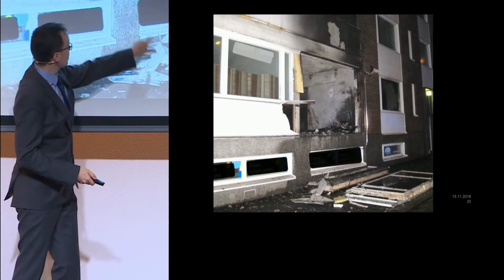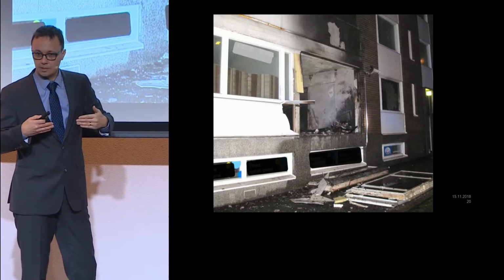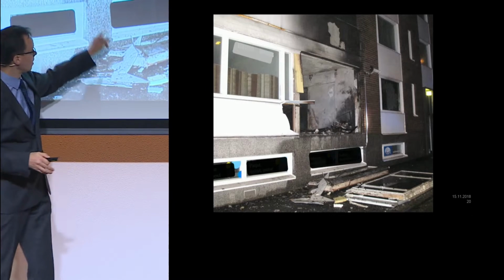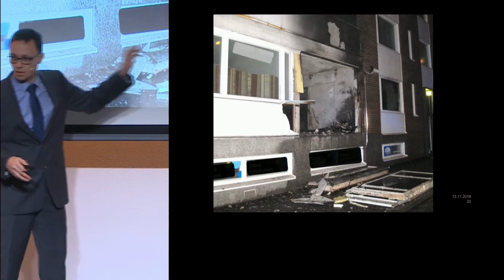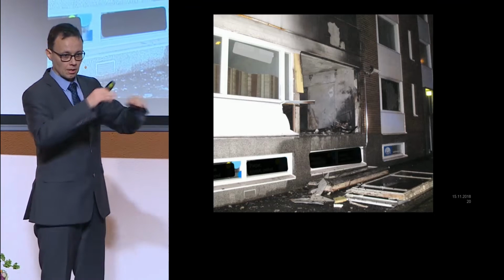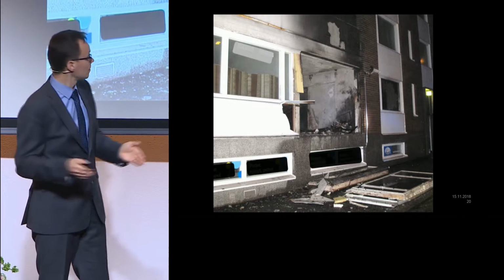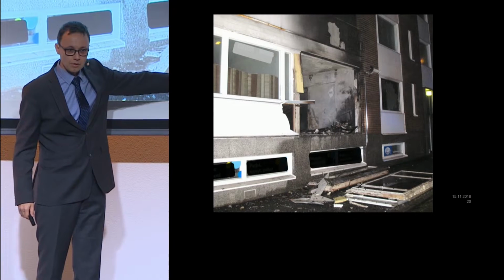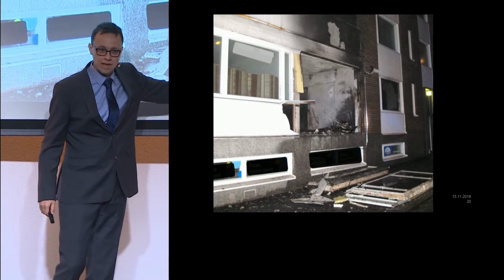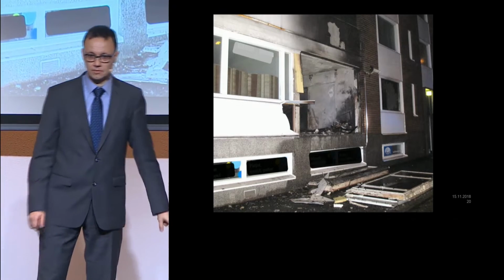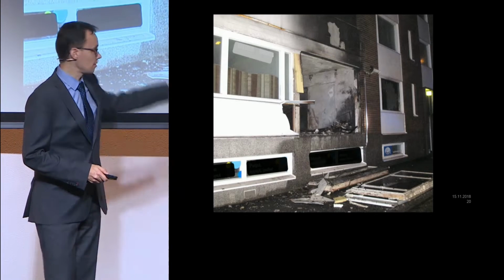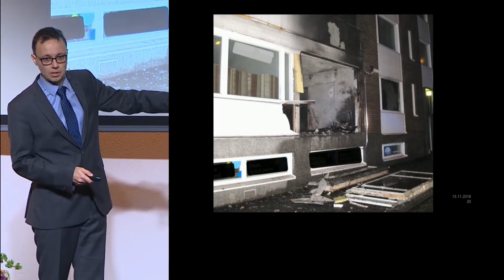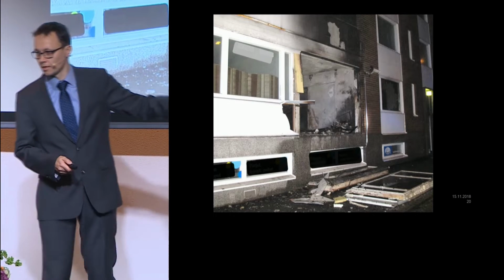What's here is the outer wall element, which is a kind of lightweight element with a wood frame, wall element, and window element, and it has been attached to the concrete element structure. There are no burns, no fire damage in these structures. They have not been charred. They have not been even severely heated. So this thing has come down from the wall before it really got hot. And it probably got really hot because it came down, providing a lot of air.